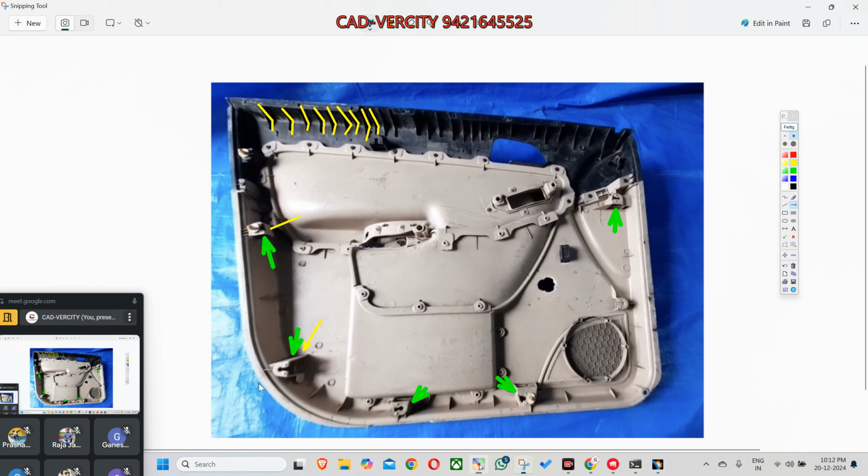So Ganesh, here you can see. Where is the opening of the doghouse? Is it inside of your design or outside of your design? The opening of the doghouse. Inside. Inside, okay. So your lifter is going to slide inside. So that's why we will use a lifter. And suppose imagine that there is one doghouse like this and we are clearing this face outside like this. So in this case, you will use a slider. Agree? Yes.